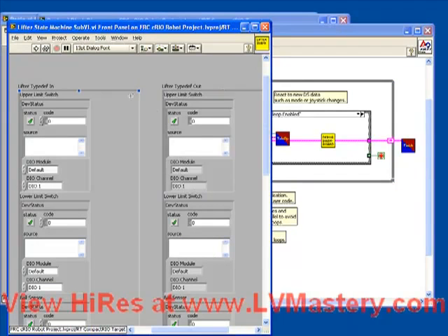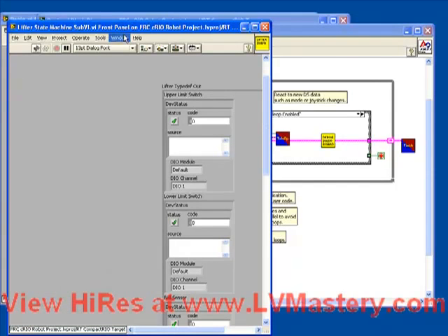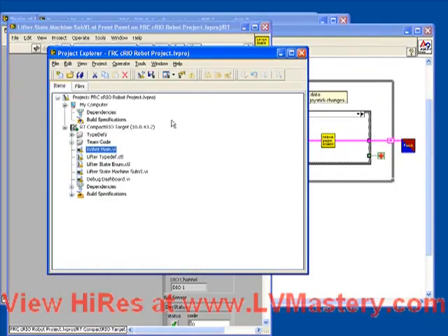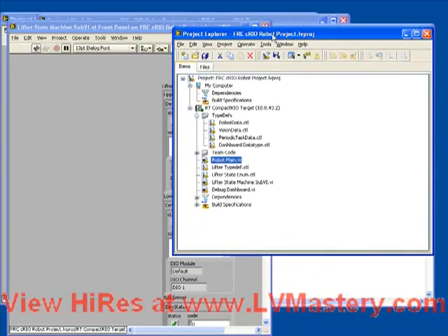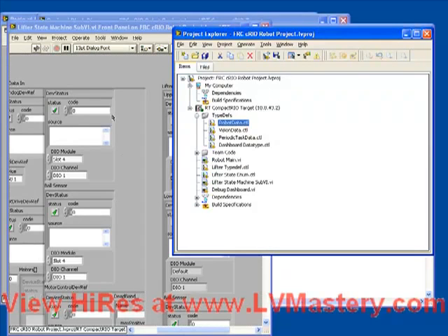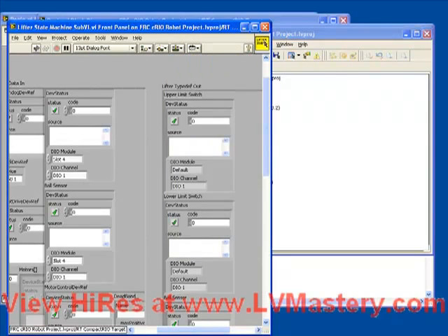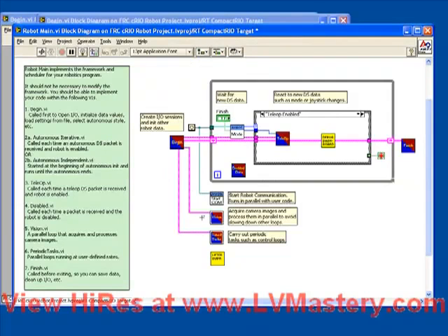So we'll open up our sub-VI, delete the lifter type def in, go to our Project Explorer, type defs, and just drag our robot data right onto the front panel here. Then we edit to show connector and make sure that gets wired in here, and then wired in here.